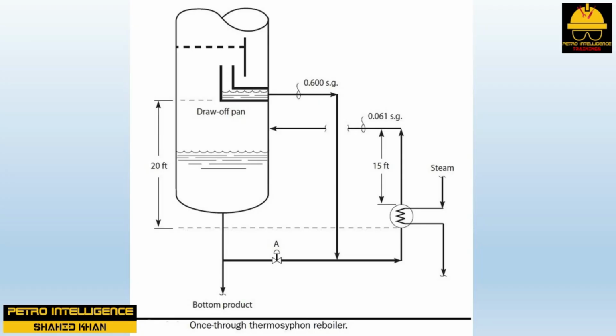Loss of once-through thermosiphon circulation. There are several common causes of loss of circulation. The common symptoms of this problem are inability to achieve normal reboiler duty, low reflux drum level, accompanied by low tower pressure, even at a low reflux rate, bottoms product too light, reboiler outlet temperature hotter than the tower bottom